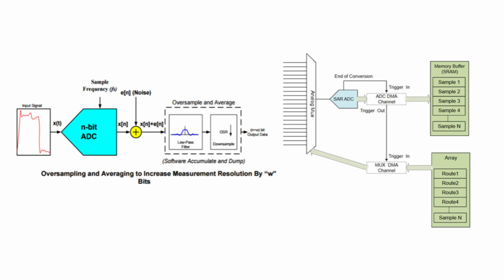A moving average filter is very common and conceptually simple. You keep a buffer, like an array, of the last m readings. Your filtered output is simply the average of all the values currently in that buffer. As a new reading comes in, it replaces the oldest one in the buffer, and you recalculate the average. So it smooths things out over the last m samples. Precisely. It's great for smoothing out random noise spikes. The bigger m is, the smoother the output, but the downside is it introduces more delay, or lag, in reacting to real changes in the signal.